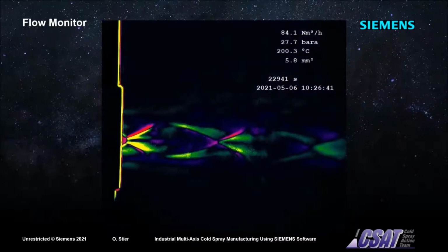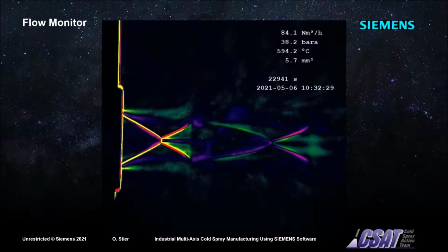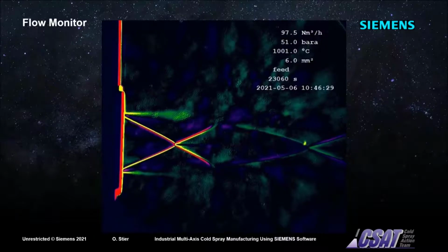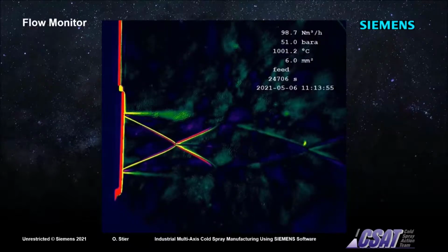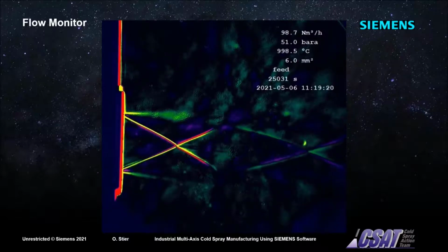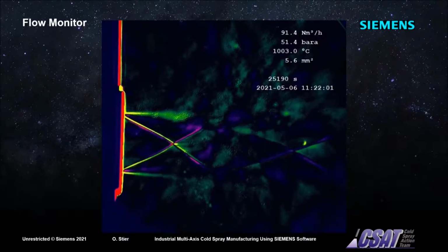Nevertheless, the particle velocity at the nozzle exit starts to decrease well before the final clogging. When the nozzle wall ceases to be hydraulically smooth, the internal boundary layer grows, dissipation increases, and the effective expansion ratio drops. Transient changes of the flow direction may occur. Continuous observation of the after-nozzle flow by the Siemens monitoring system reveals such erratic flow periods, signalizing imminent clogging well before particle velocity drop becomes critical to part quality.